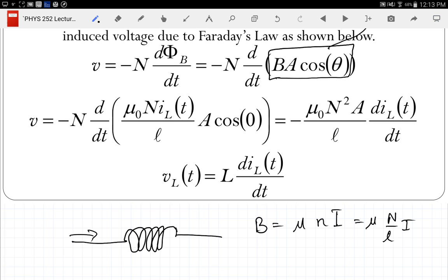A capacitor stores energy, right? And it gives it back. An inductor is supposed to store energy in a magnetic field and give it back. But if you have some work involved, that means you're going to lose a little energy. Well, what did we call the devices where I push charge through and I lose energy? Resistors. So we have an effective resistance for an inductor that's based on how much work is going to be required to align the little domains.